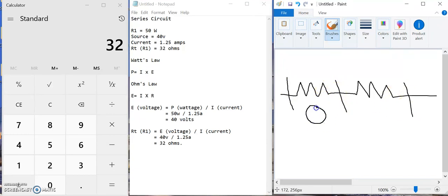Calculate out what you need to calculate for here, and then calculate what you need to calculate for here. Remember how current and voltage flow through circuits. Well, voltage doesn't flow, but remember how current and voltage are applied to circuits. Current in series is the same all the way through. If you have watts over here, and drop, remember drop is how much that resistor is using, you can figure out your amperage. If you figure out your amperage, you know that amperage is applied to this resistor as well.